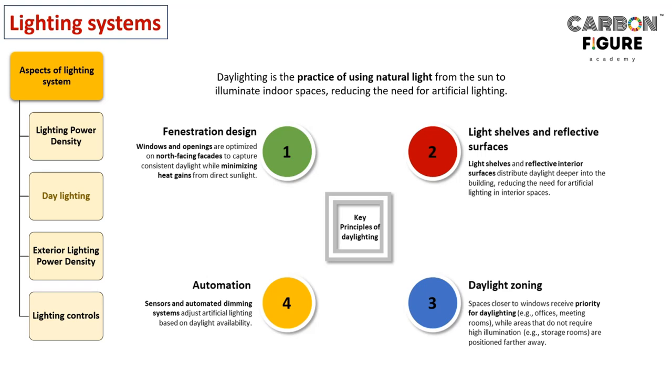That's a very detailed area, but try to understand it for the Indian context. We need to optimize the windows and openings on north facing facades, right? Where you are able to capture consistent daylight while minimizing the heat gains.